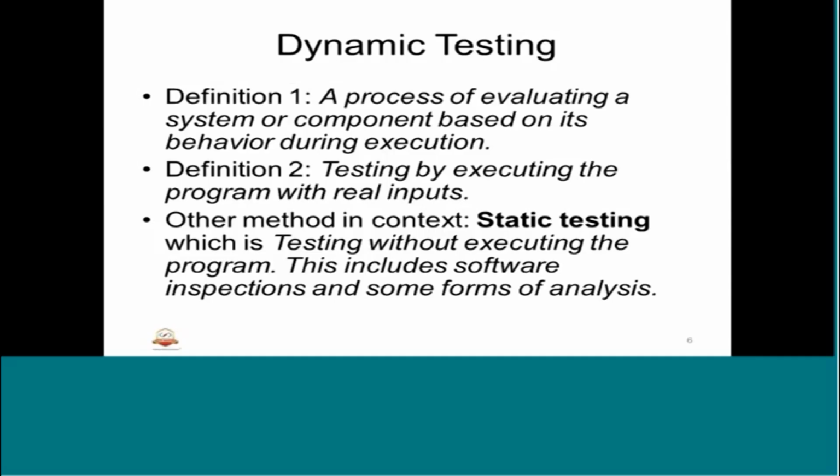The other method compared to dynamic testing is static testing. This is done without the need of executing the embedded software system. So we studied dynamic testing with a couple of definitions. Also, we know the other method, static testing, which doesn't need the program to execute. So this could be software analysis, walkthroughs, inspections, etc.